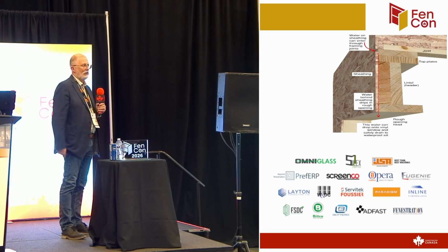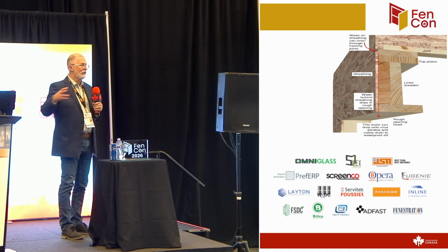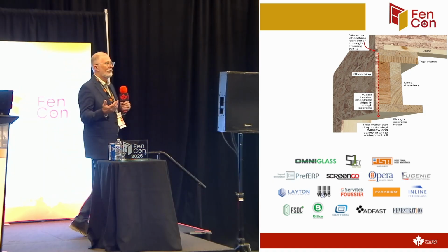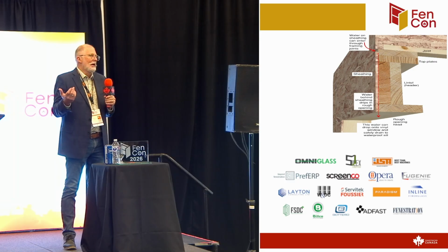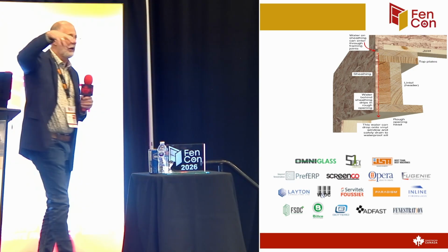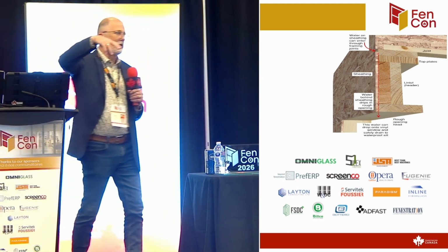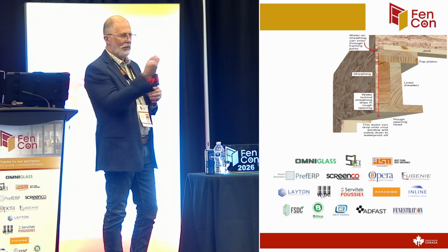But on a passive house, where it's a really deep sill, are we seeing a dead pocket? It really comes down to whether that boundary layer of air is influenced, because your windows, what's the best window you can buy on the market right now? An average R8, R9 maybe? So the air in the middle of your house, if you're operating at code conditions, 21 degrees, 35% humidity, has tons of ability to absorb that moisture.